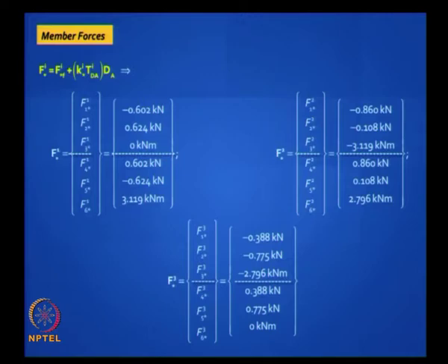You can find the membrane forces. Now you get shear forces and bending moments in addition to axial forces, but they are of small magnitude. You see that value which we got, 0.9 for the second element, the exact answer is 0.86, which is close to 0.9.